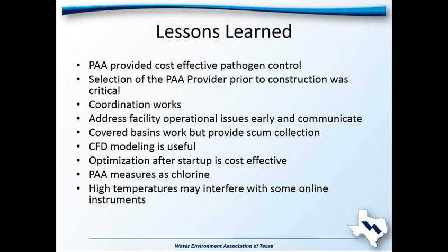One thing we included was covering the basins. At that time, we had been told that algae growth was something people had seen previously. So we did cover the basins, and we have not seen algae growth, but we have seen a buildup of scum collection over time. If we had it all to do over again, we should have added scum removal, a way to get it out.